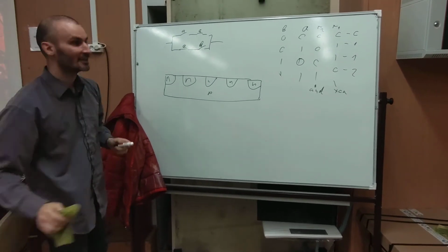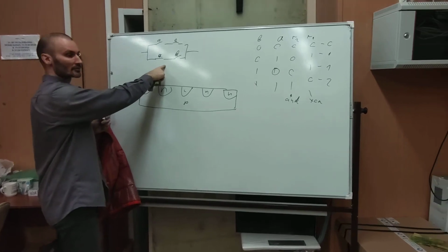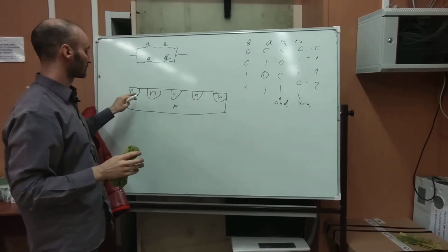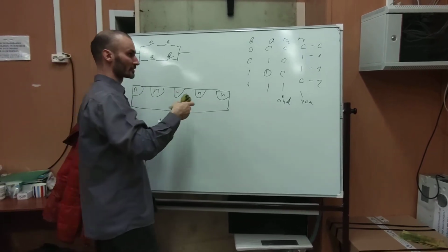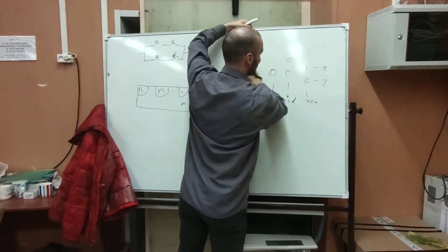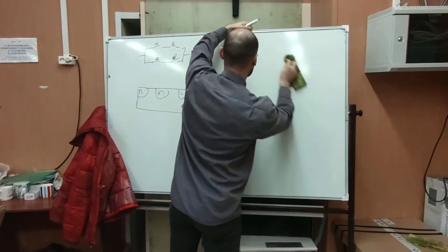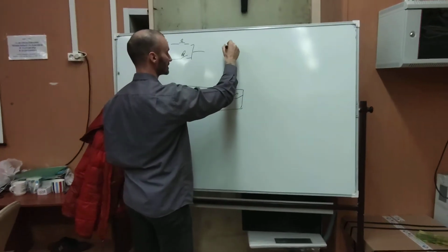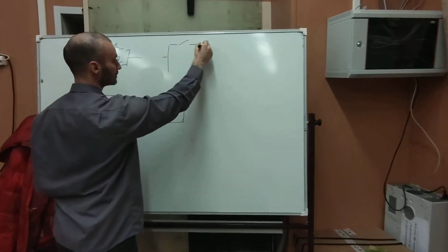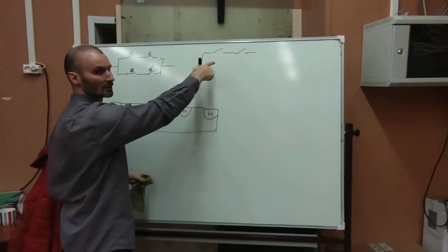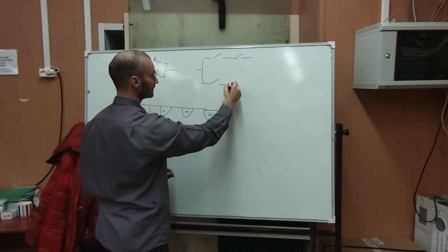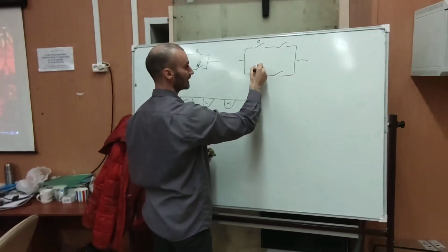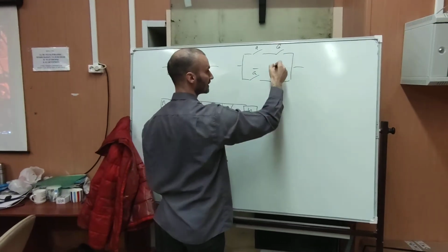That's not the end. Okay, so another way of showing the same schematic is using all N-types. For our substrate, we will use all N-type transistors because they occupy less space and because it's easier to make them. Quite a few reasons for that. Okay, another way to draw the scheme is like this. So this is like input, and we will use only N-types, so only normally non-conducting switches. That will be A, and that will be not A. That will be B, and that will be not B.